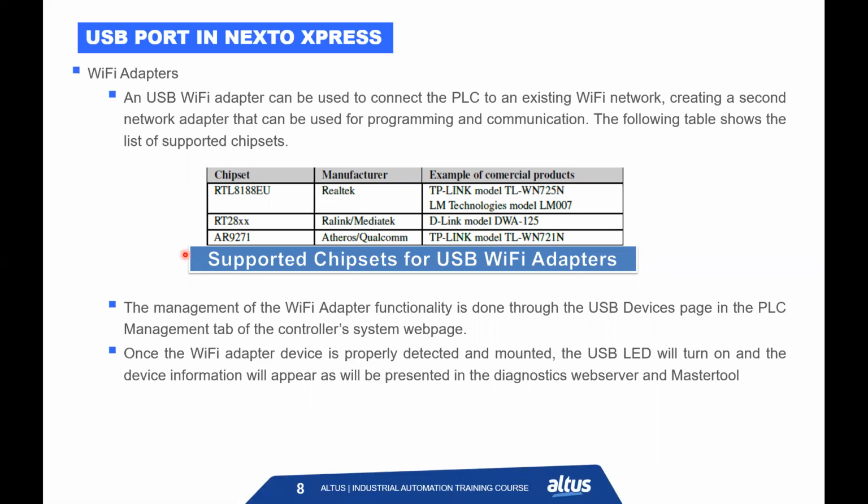It's a very useful tool, for example, for building automation. For example, you installed an Express to control air conditioning, heating, lighting, and you don't have infrastructure cable to connect to the Express, but you have a wireless network protected with password and cybersecurity in your wireless infrastructure. So we can use this wireless infrastructure to connect the PLC that is, for example, controlling the elevators, water from the building automation.